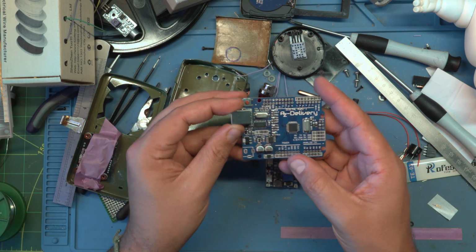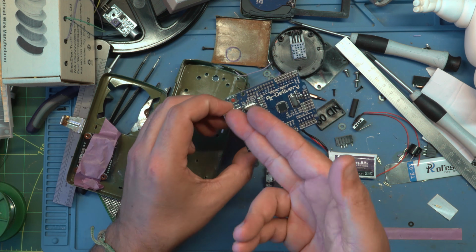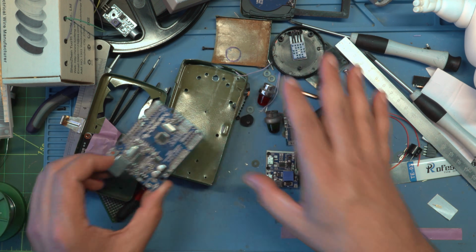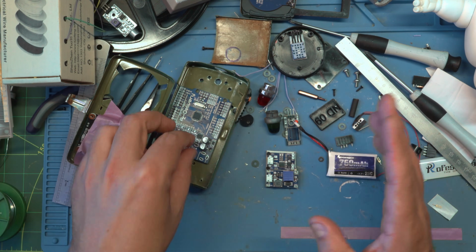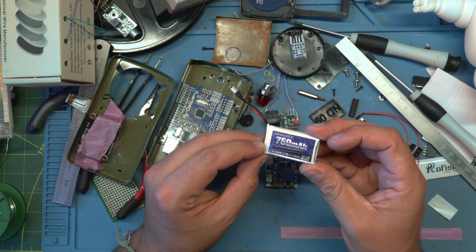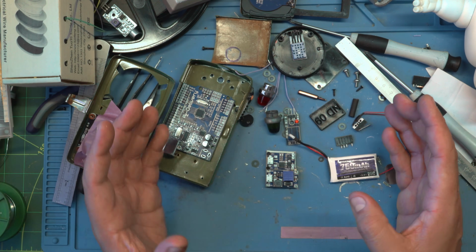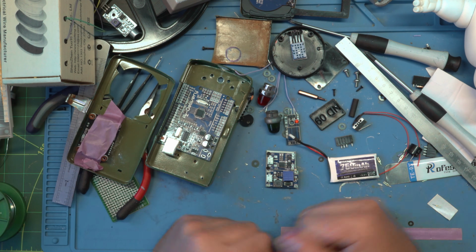So I hoped I could get around this. Of course, you know, the Arduino board works with 5 volts supplied by the USB port that powers all the auxiliaries. I tried it with 4 volts and it worked, but I tried it with battery power now, which is 3.7 volts, and it seems to be barely not enough to power it, at least to get the same readings as in my test setup.